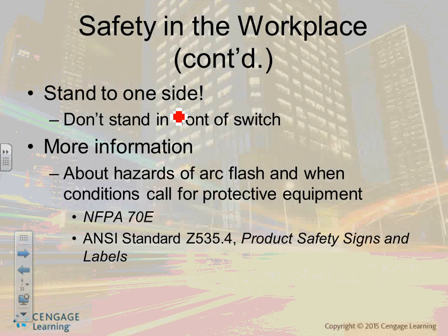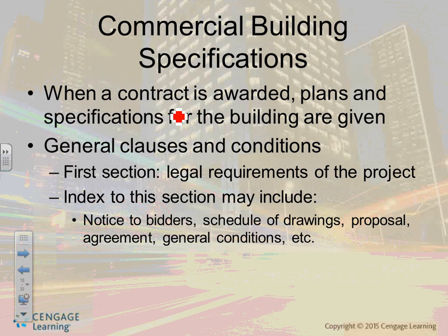So that's why you see a lot of electrician guys, when they open the switch, they don't stand right in front and open it this way. They go this way and open it to the side. So if there's an explosion, your chance of surviving is higher. So a couple of tricks, guys, for that one. More information about all this hazard, guys, as you move on. And NFPA 70E will give you tons and tons of info about electrical safety, which, if you're a project manager, you'll be very aware of.